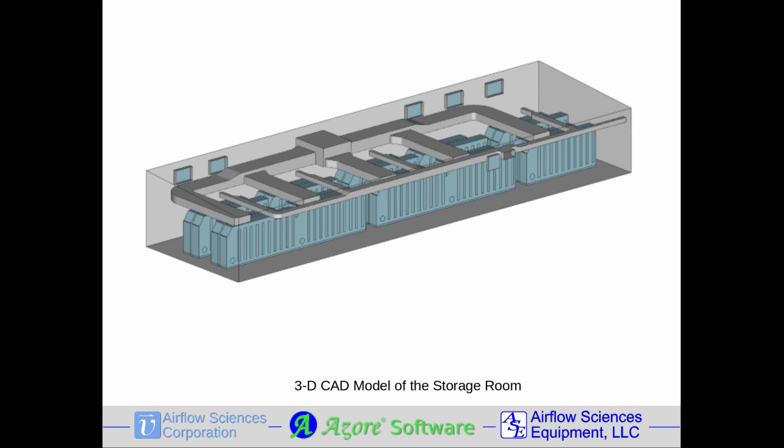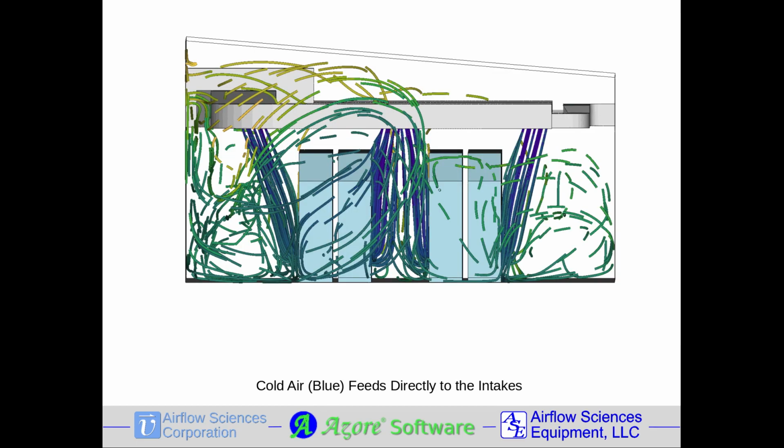Each group of battery racks is mounted inside a cabinet with its own internal cooling fan that pulls room air in, then exhausts the heated air out through a series of vertical openings adjacent to the racks. An example CFD simulation of air flowing through a room is shown. It takes into account the temperature and velocity of the air as it enters the room through the HVAC system and follows the flow as it enters and exits the battery units. The return air vents pull warm air out of the room and back into the cooling system.